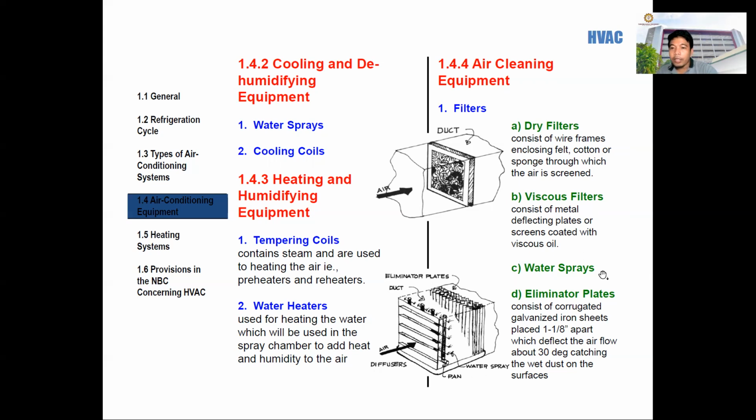We also have water sprays, and the eliminator plates, which consist of corrugated galvanized iron sheets placed 1 and 1/8 inch apart, which deflect the airflow about 30 degrees, catching the wet dust on the surface. So this is the eliminator plates, this one.